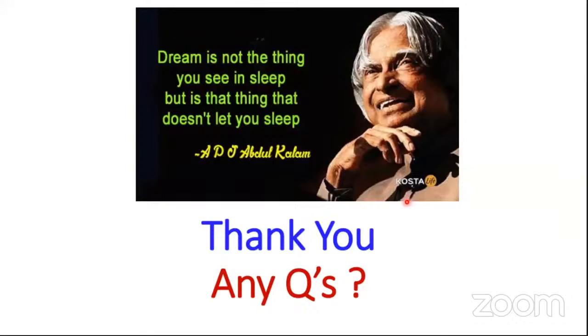Like for example, if we take the laser scanning speed, it is very similar to, for example, the welding process when we do, and what is the welding speed that we use to weld a bead, right? So in that scenario, if we are using a very high scanning speed, then the scenario that we are going to encounter is that we are going to have improper melting of the metal powder, right? And then once this improper melting happens, then there could be associated defects, like as you mentioned, unmelted zones will be there, some